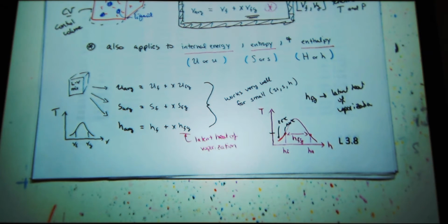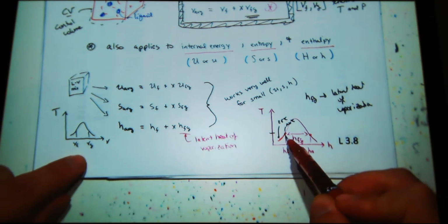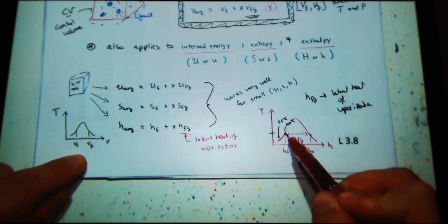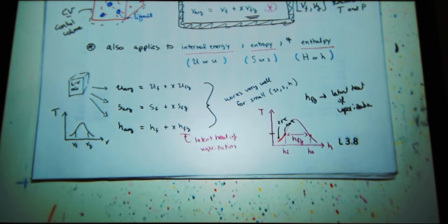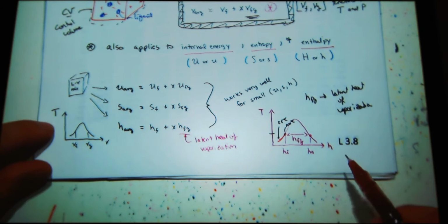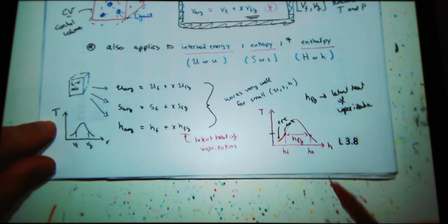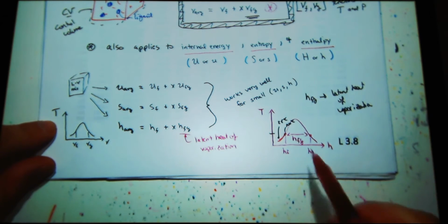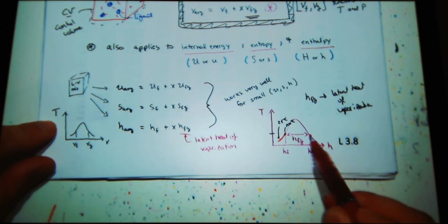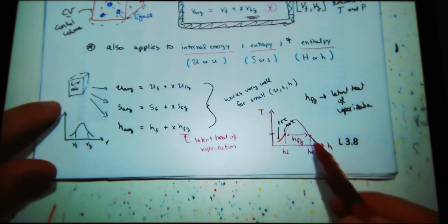So the quality is, if I'm 100%, it tells me the total amount of vapor in my mixture. So if your quality number, the X number, is 0.5, you're in the middle, and you only need that much more to get there. Okay, got it. But if my quality factor is 1, I have 100% vapor, so I know I'm going to be along the saturated line.